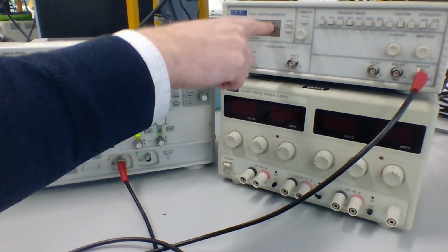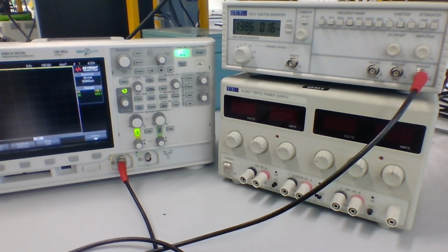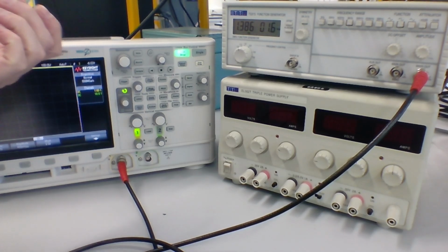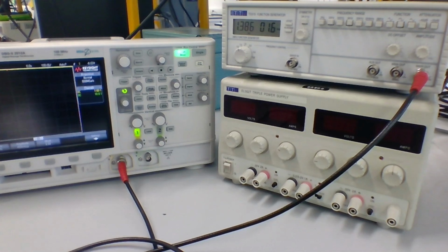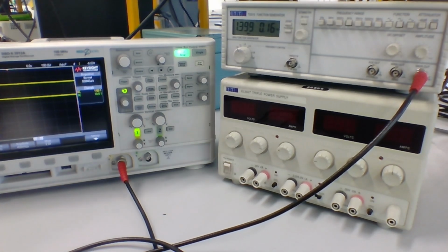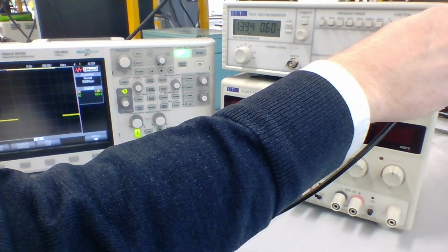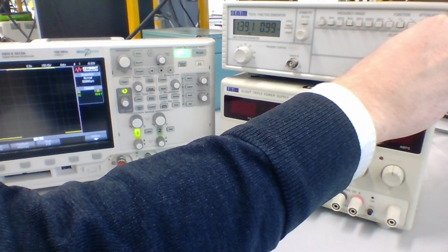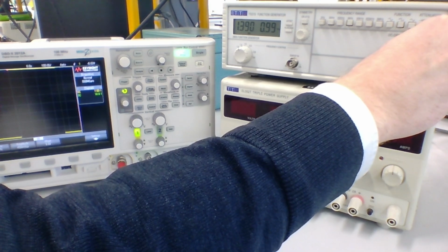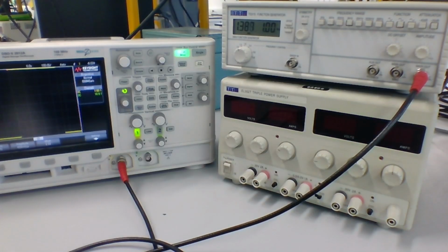And these change the scale or the range of this voltage. One by 20 decibels and the other by 40 decibels. Which, again, we'll cover more when we talk about filters. For now, I think of that as just a larger or smaller scaling factor. So if I press the 20 dB attenuation, this now drops down to 0.16 volts peak to peak. I can then dial that back up to our desired 1 volt peak to peak. So that's our voltage scaling set.